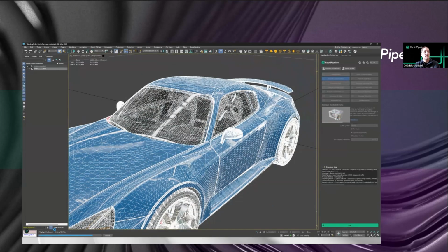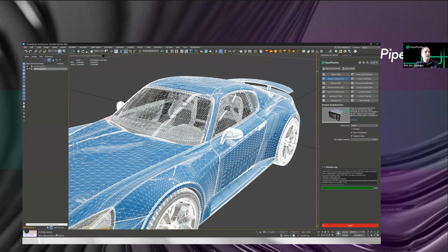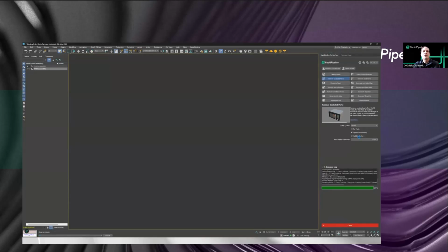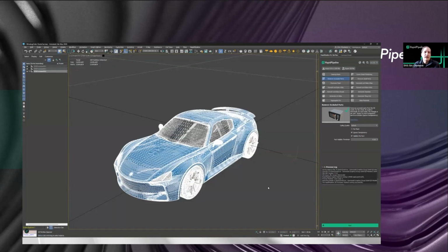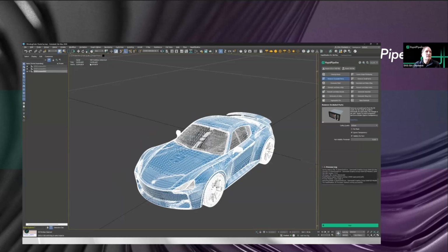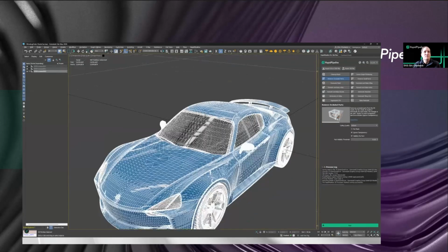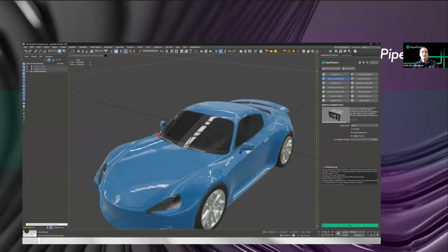Now it's going to do the same thing. It's going to export out to an FBX intermediary file and run it through the executable, behind where all the power lies. It's super efficient code, and it's going to compute that triangle visibility for all the surfaces. The other thing it does is that it does it per part. So it's done here, at 2 million instead of 2.8 million. It's now got down to 2 million and it's gotten rid of those surfaces inside.